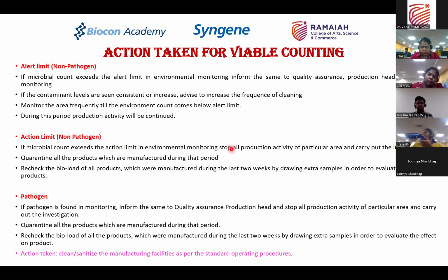What should be done? The production has to be stopped. The complete production has to be stopped. Then the information has to go to the production head and the quality assurance, production is completely stopped, and there should be an investigation. What is the source of this contamination? From what region is this microbial load coming? And all products which are manufactured during that time have to be quarantined. There should not be release of any products if the action limit is reached.